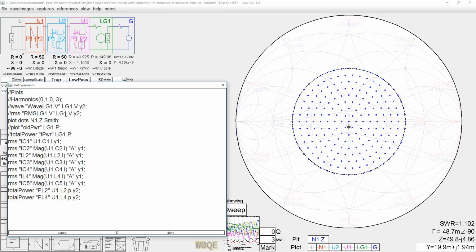It's not turned on right now. We'll turn it on. A harmonic amplitude of 0.3 of the fundamental. That puts the harmonic at 20 log of 0.3, which is 10.5 dB below the fundamental. This is a really bad amount of third order harmonic, and probably more than most normal amplifiers would have, but it's representative of somebody who builds a circuit and is pushing things. So this is probably a pretty worst case. And again, we're trying to size the filter accordingly.